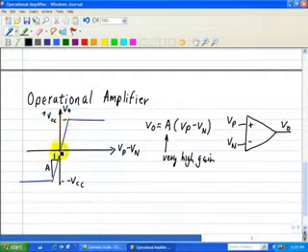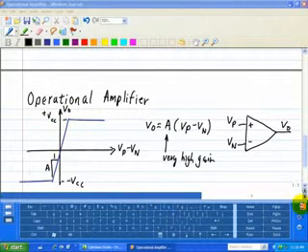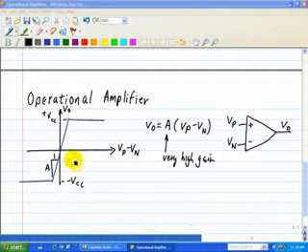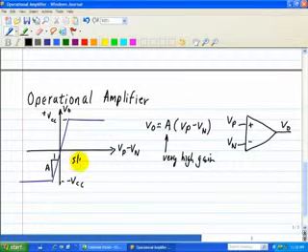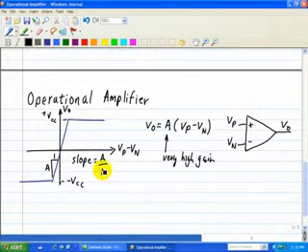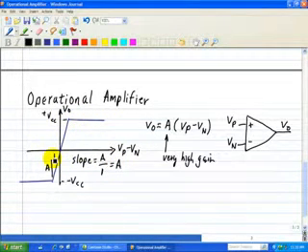So here along this linear region, this line is our gain. Our slope has a rise of A and a horizontal run of 1. So in other words, the slope has a gain of A, and this is a very steep slope. As I mentioned before, it has a very high gain, such a high gain that it saturates very quickly to our positive and negative power supply.